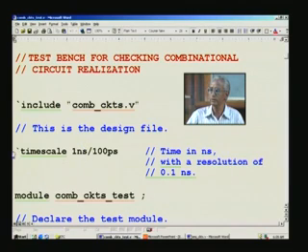In that case you have another statement, once again a tick and timescale, a space must be given, then say 1 nanosecond, or 1 microsecond, 1 us you can put here, and you can also specify how much resolution you want. For example, a 0.1 nanosecond resolution, 100 picoseconds meaning 100 by 1000, so it is 0.1 nanosecond, and that is what is put here.